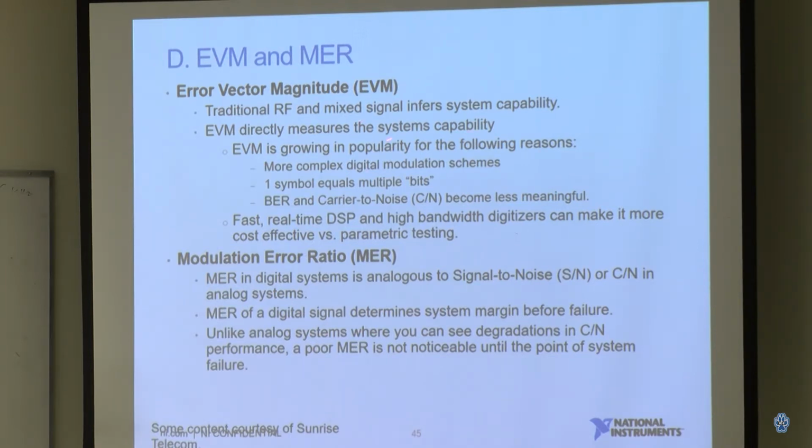It's not as good as EVM for determining how good your signal is. EVM is the main quality control parameter you're going to spec to evaluate your signal, because if your device has really big distortion and a lot of noise or amplitude inaccuracy, your EVM number will degrade a lot. So people use EVM to diagnose your system.